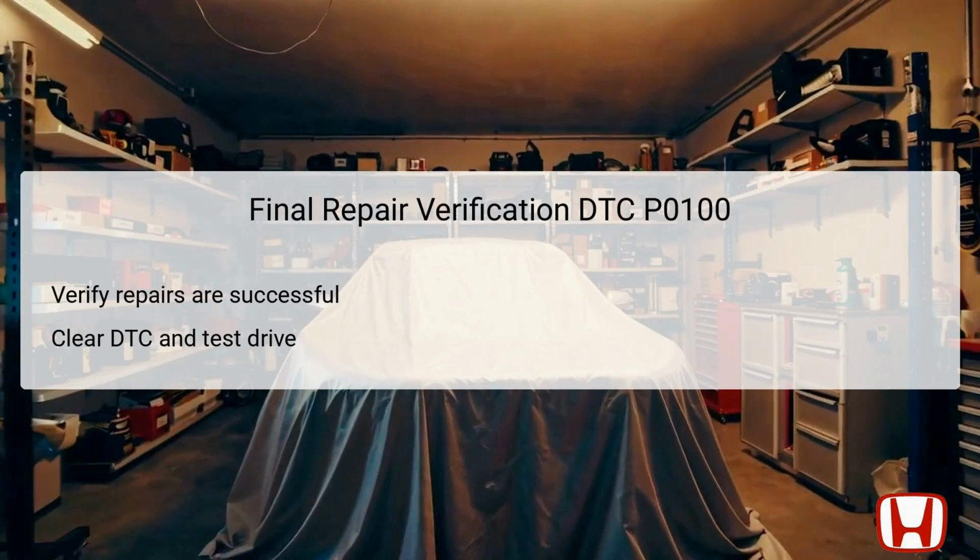It is critical to monitor any sensor's feedback and check whether the MAF sensor's output frequency is now within the specified limits. If the DTC remains cleared following this test drive, it strongly indicates that the repairs were successful and that the vehicle's engine management system is functioning adequately.